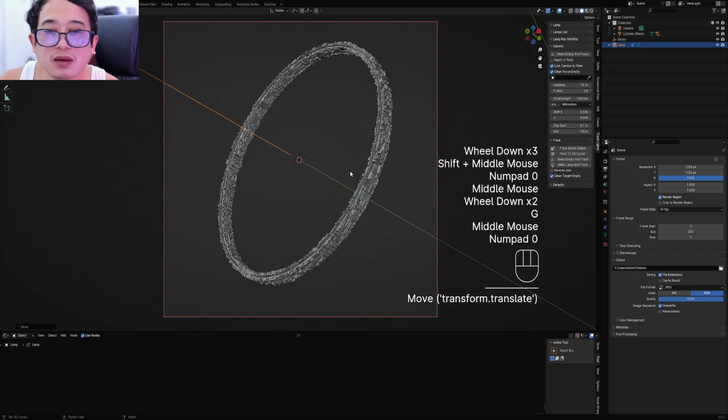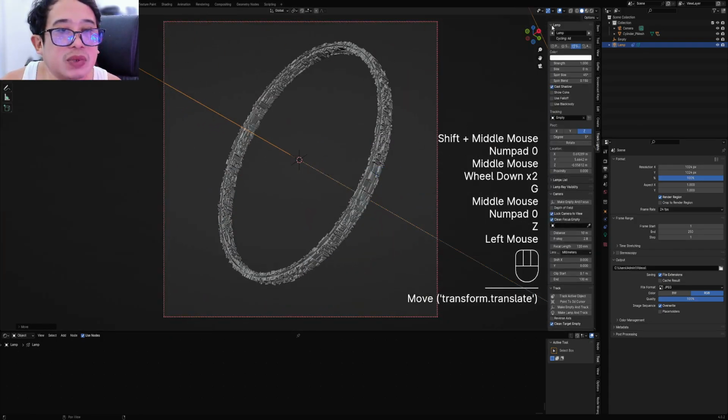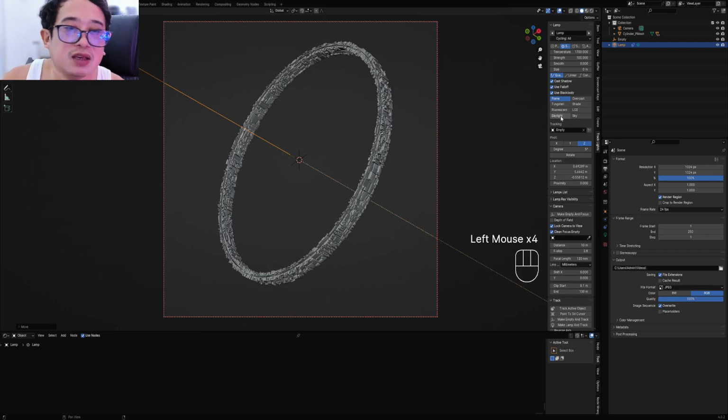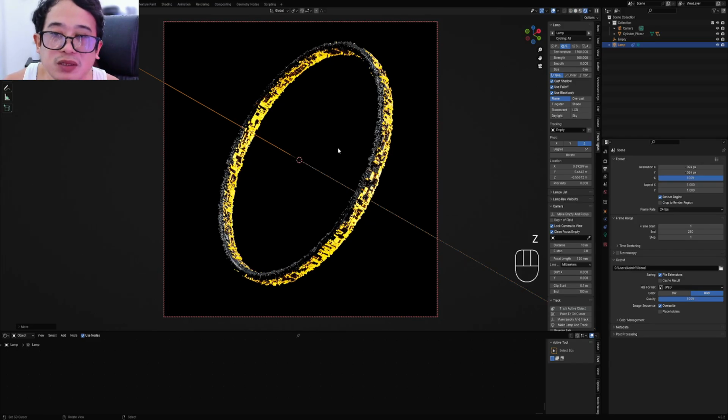In lamp, set the type to sun and turn on use falloff and black body. So you can use Kelvin settings for flame, tungsten, fluorescent, daylight, overcast, shade, LCD, and sky. I got the numbers for this from the internet. So yeah, I don't know if they're accurate, but